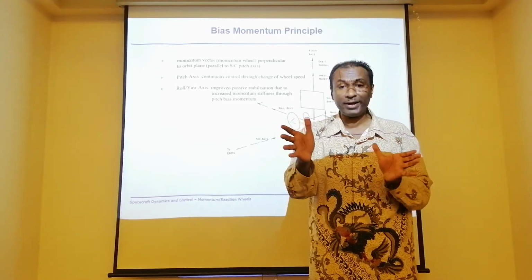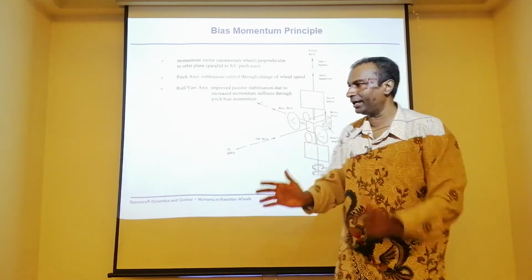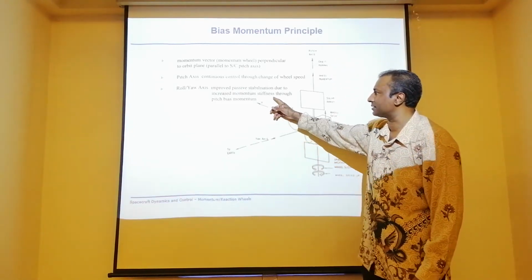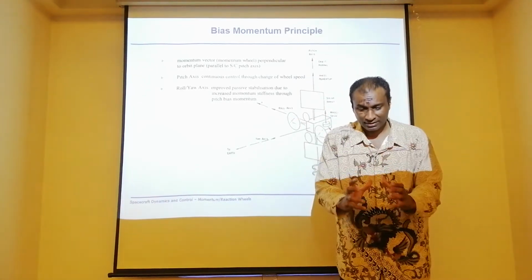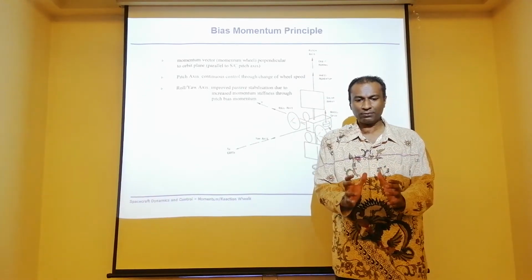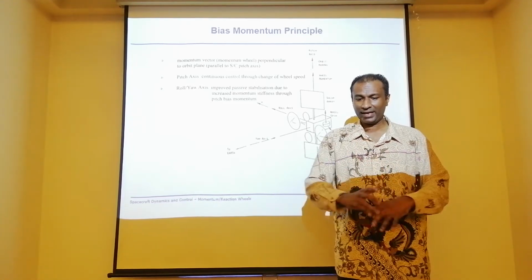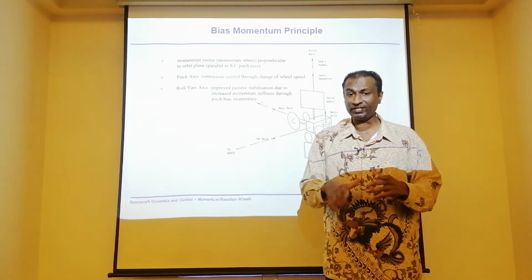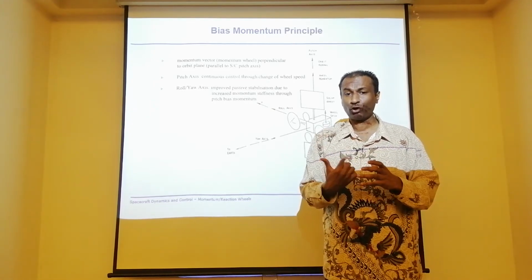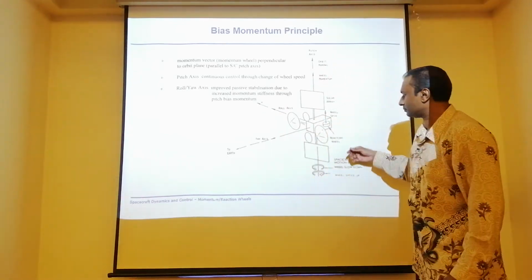The roll and the yaw axes are basically going to be quite stiff. So it increases the stiffness of the roll and yaw axes by putting the momentum wheel in the pitch axis. But that is all. It gives you a stiffness to roll and yaw. But don't forget, for the pitch axis, it can actually produce active torque when you start speeding up the wheel. Okay, go on.